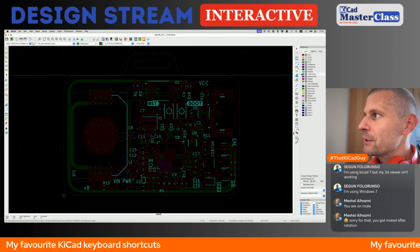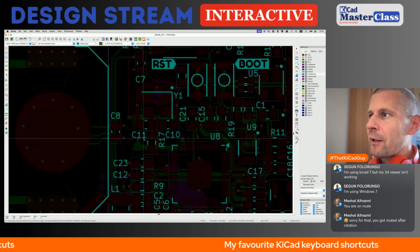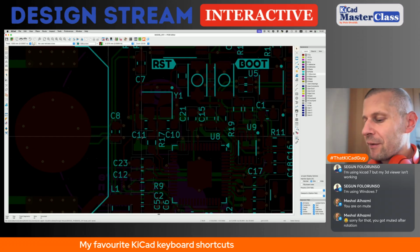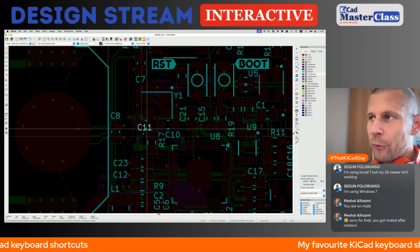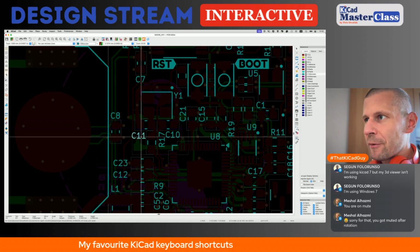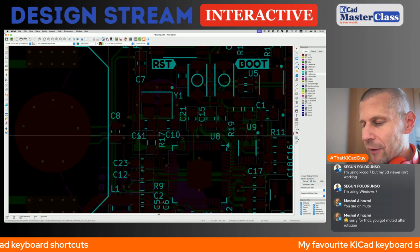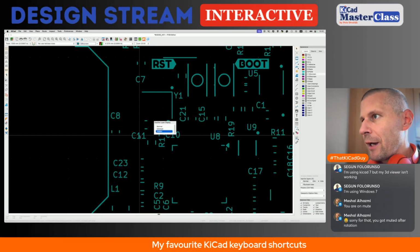It's very useful. I'm using most frequently the dimmed version. For instance, when I'm placing labels or reference designators in the silkscreen. So I enable this mode. I can see where the footprints are. So I can see that, for instance, this label can't be placed across the footprint, but I can see the details. I can see the picture. So then I can comfortably place the label or reference designator. So H.